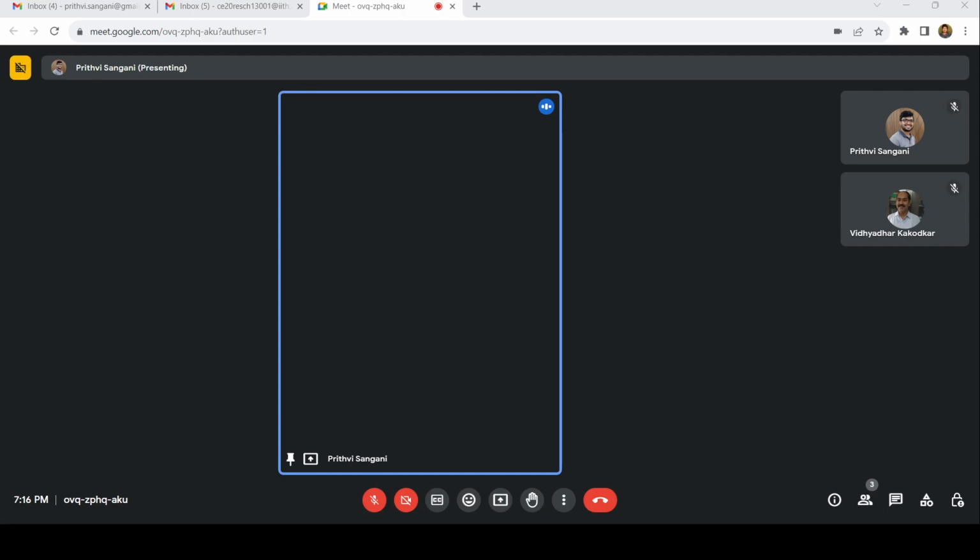Okay. So if it is 16EI, then what is delta B? Delta B is nothing but delta 1 plus delta 2: PL cubed by 24EI plus PL cubed by 16EI. This is turning out to be, 2 plus 3, 5, 5PL cubed by 48EI. So delta B is so and so.